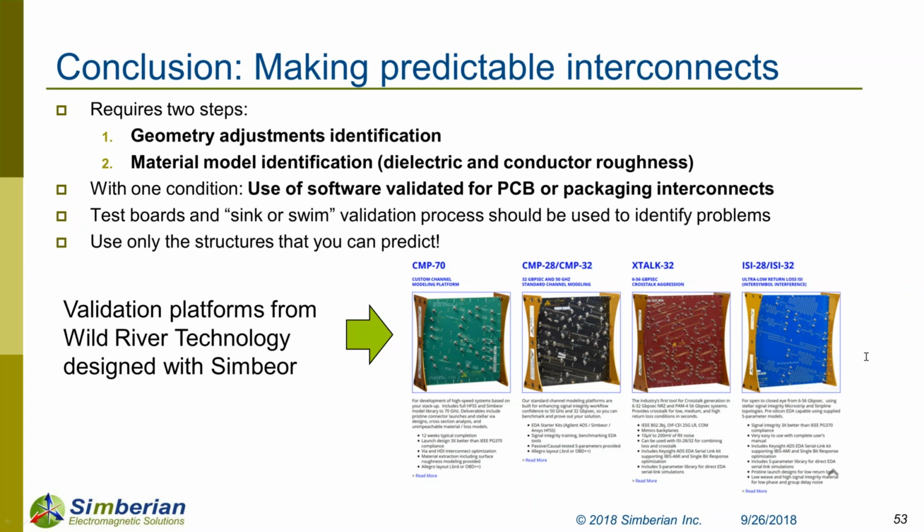And the second parameter is roughness factor, which characterizes the expected maximal increase in the losses due to the roughness compared to a flat surface. Basically, we have converted 6 different models, like Huray, hemispherical, Hammerstad, and modified Hammerstad, that we proposed a few years ago with you, Chudi, in our paper. Remember modified Hammerstad? That's the second parameter we added. Now we use it for all models, including this Huray snowball and this Huray-Bracken causal extension of the model. The first parameter you can get even from spreadsheets sometimes, for just one side, by the way. So that's important.